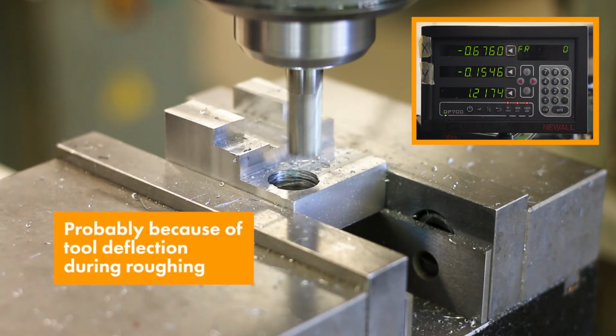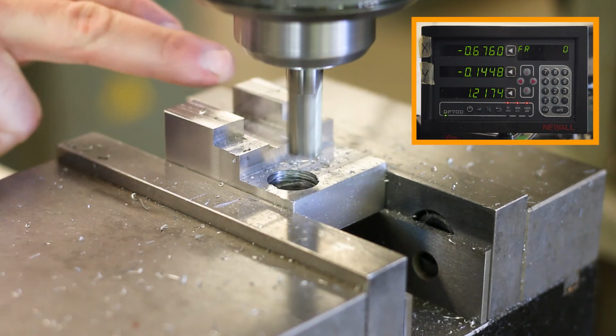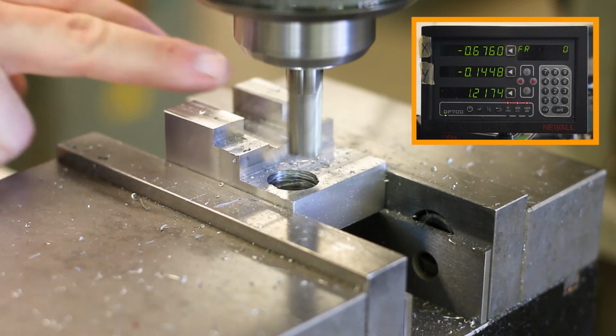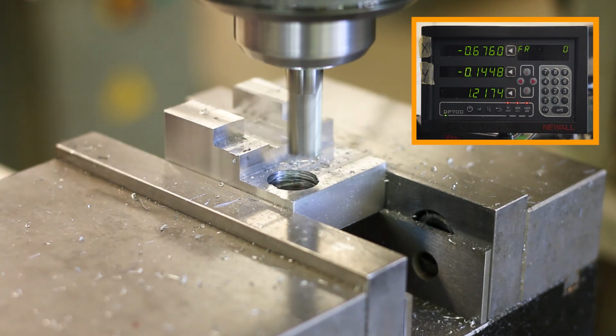So I'm going to go ahead and take a roughing cut. So I'll set this to 145 and take a cut, and then come back and take another cut at 155, just so that we're taking about the same amount of material off of both sides, so that we're just going to get a little bit more accurate comparison between the two surfaces.